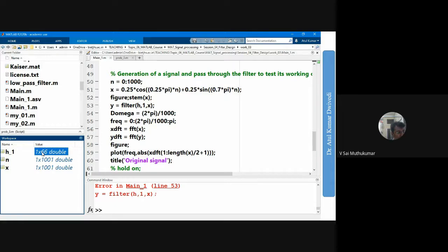Filter order and all will be frequency range dependent, sir? Or should we always work only for lower filters? H should be lower. Yes, H should have a smaller number of coefficients. That is the requirement. The traditional designing methods like the windowing technique have one fixed equation of order calculation, that is the order. But the modern techniques can reduce this order.